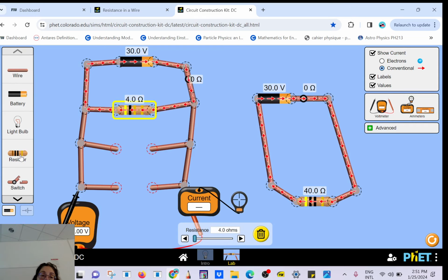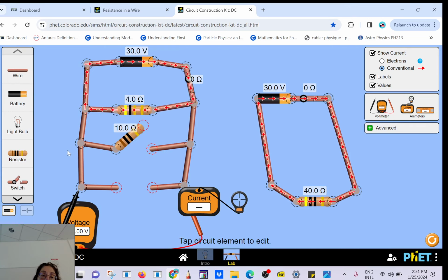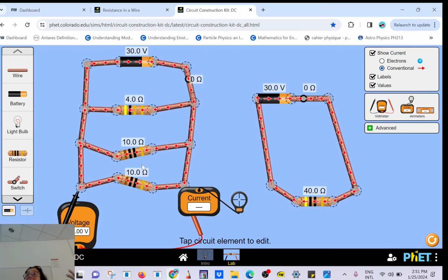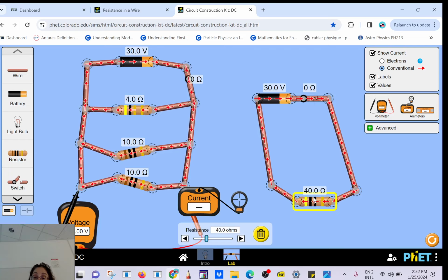So this is in parallel. You know it's in parallel when every single load gets the same voltage. When it's in parallel, everything happens like it's alone. It doesn't care about the other ones. They are not interfering with each other. But if you are in series,